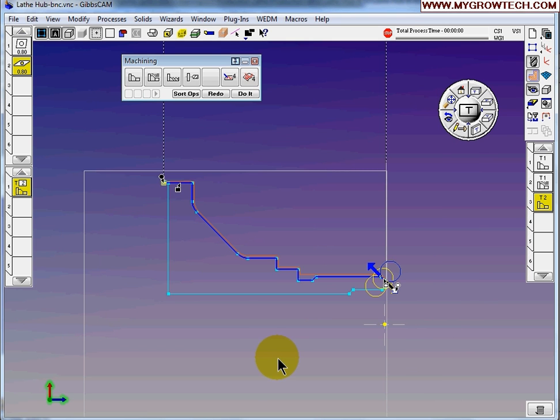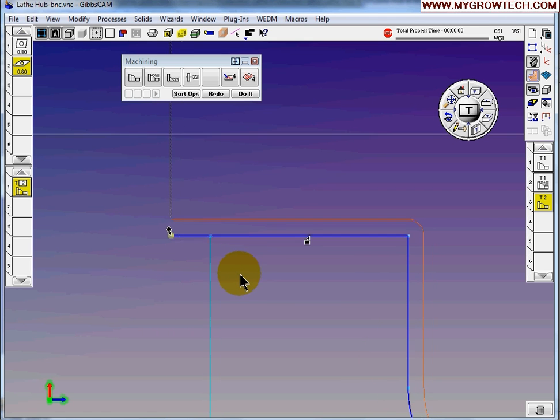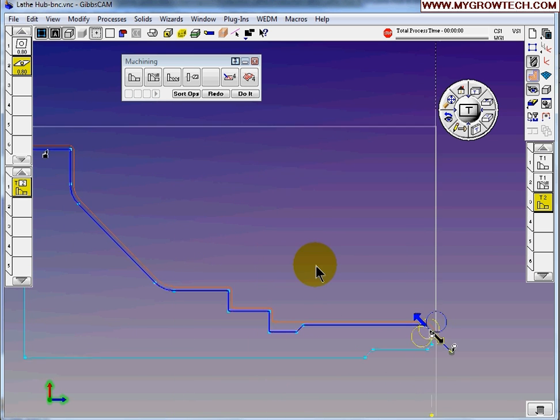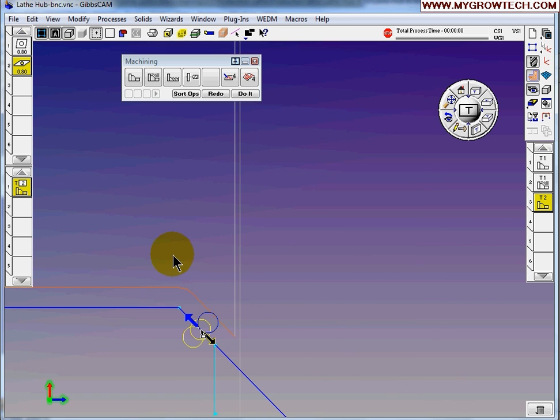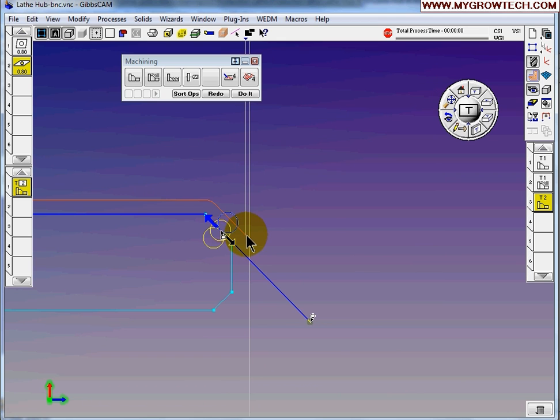Now let's check the end and start point of the finishing operation, the third operation. For the end, it is 2 mm out of the part, this is good. How about the start? It looks like we start over here, somewhere near the part. This is not the location that I intended, because I already extended the start point up to here. So why does the cutting operation never start from this point, and instead start inside the material? This is because of the parameters.